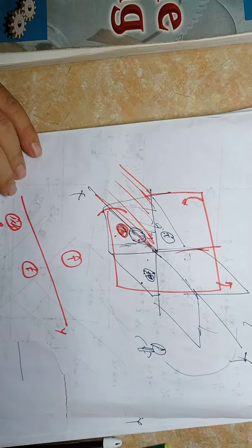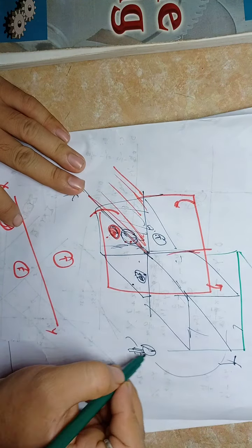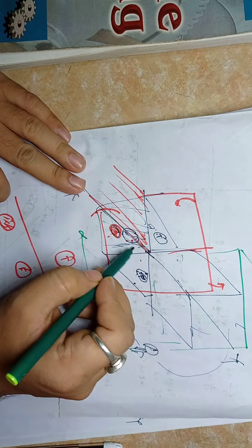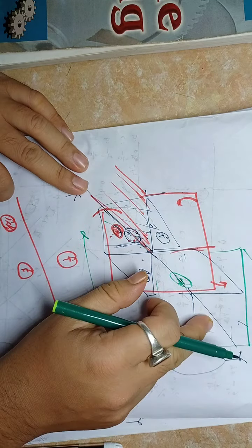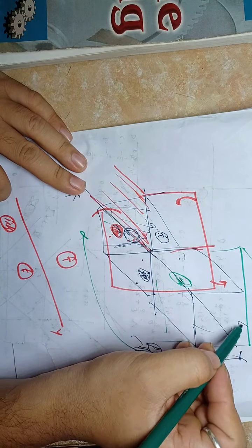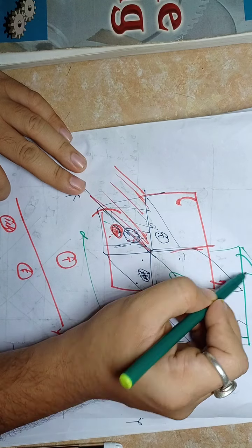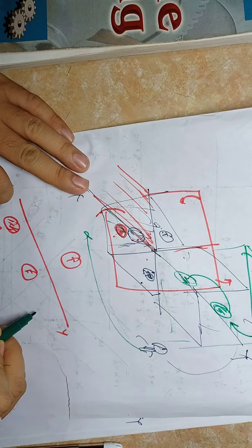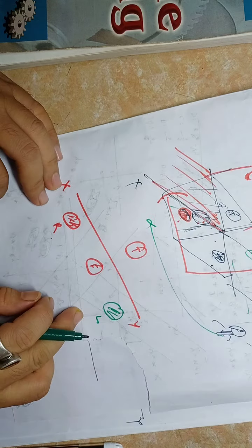So again, when you move to your left, okay, your left, and you view from this side, then it will strike there. So you have to rotate this plane like this, so that you get your view here. So your left side view comes here, for third angle position.